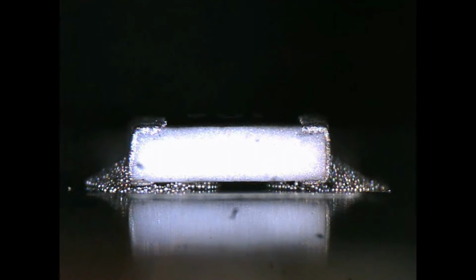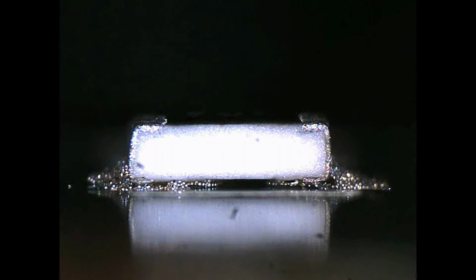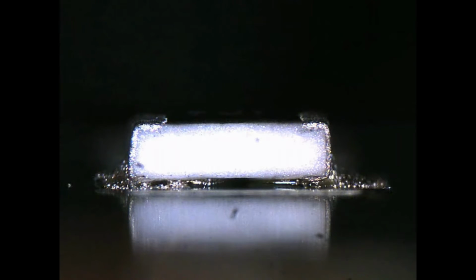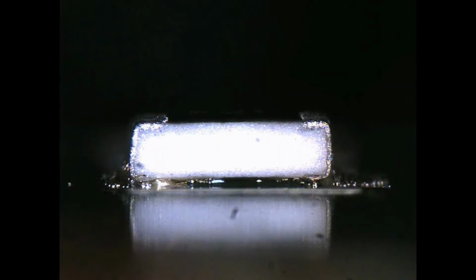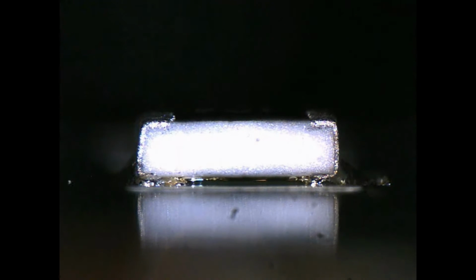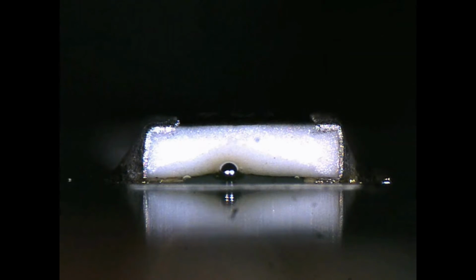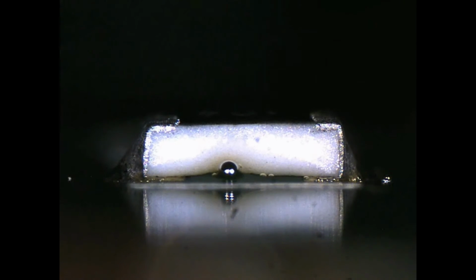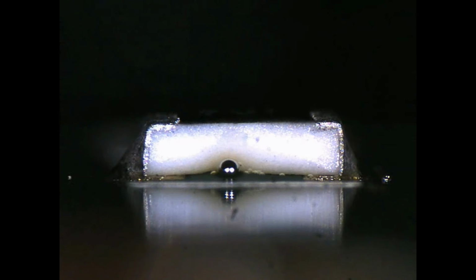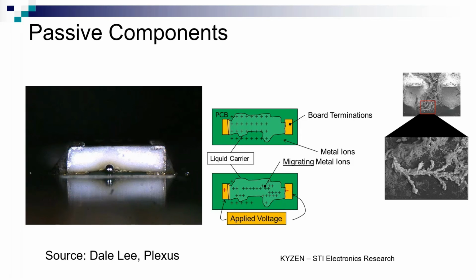What you're looking at is this chip cap going through a reflow cycle, and you can see some bubbles forming there. That's the flux as it achieves the melting point. The solvents in the flux residue are volatilizing. They have to outgas and escape, which reduces the volume of that residue and allows it to polymerize into what we typically see as no-clean residue.